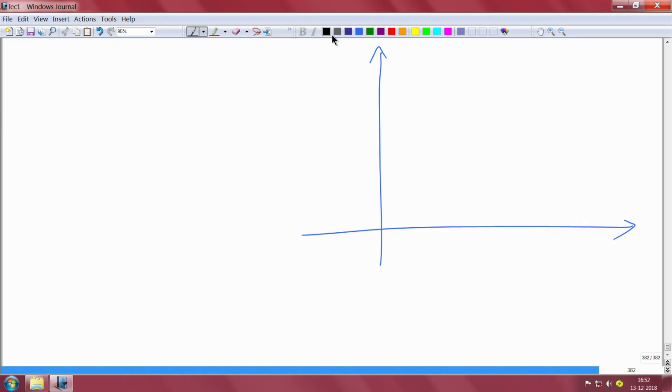So if you take just a silicon PN junction, which is not an LED by the way, you will have a forward current like this, and this cut-in voltage is probably around 0.7 volt, right? Then if you take gallium arsenide, the cut-in voltage will be around 1.2 volt, right? You can take InGaAs, it can be even less than that, because it can be less than silicon in an InGaAs photodiode. You can take maybe an InGaN green LED.